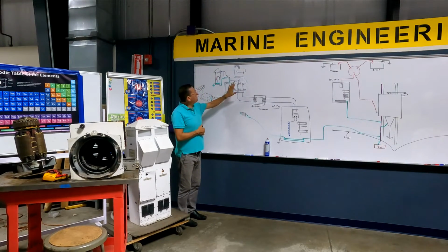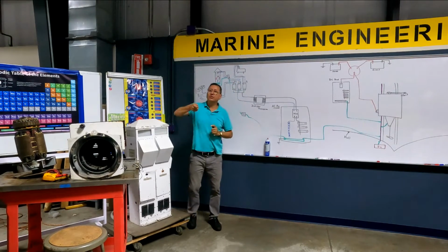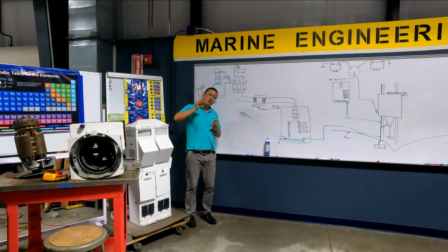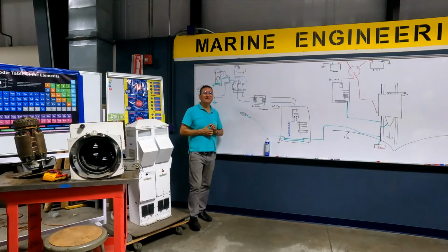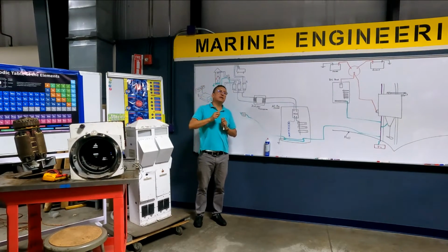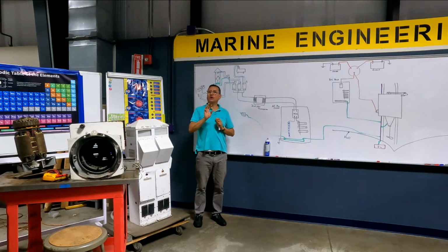The ground does not pass through the breakers. In the breakers, you interrupt hot and neutrals, not ground. The ground goes directly into the ground bus bar. Never interrupt the ground on the breaker. The breakers only interrupt hot lines and neutrals. Ready? Okay.